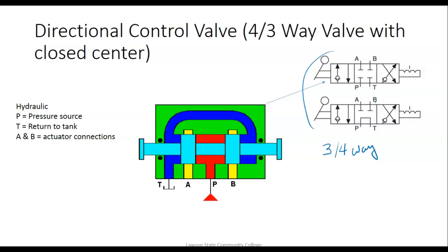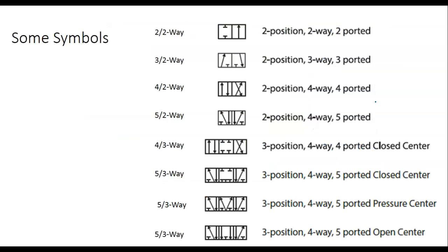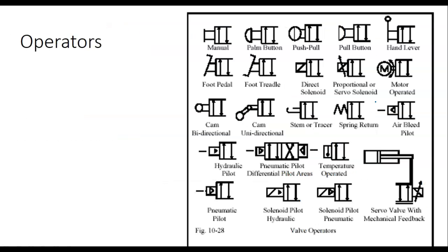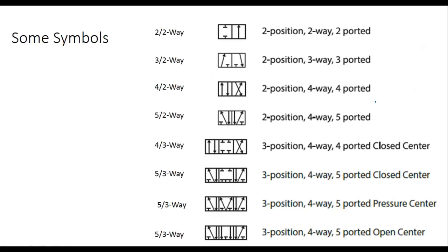I'd have to look at the Festo lab and see if they've got any in there. Oh no, we have some 5s too. If they have a 5, the 5-port valve actually has 2 exhausts, and we talked about that, right? Okay.